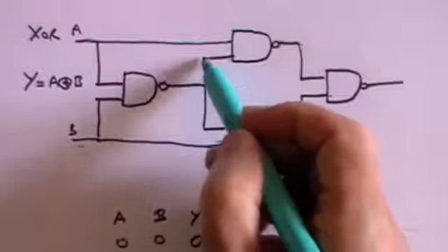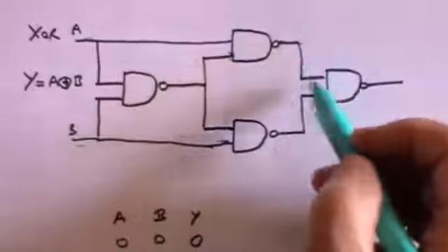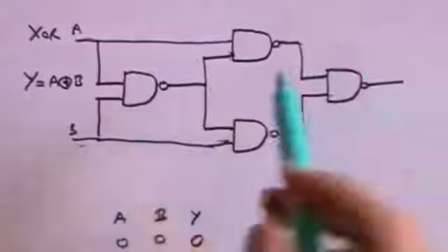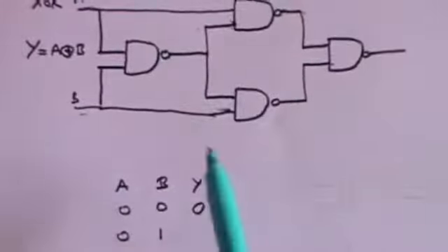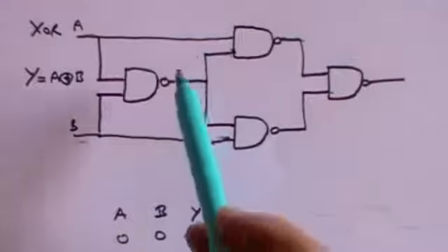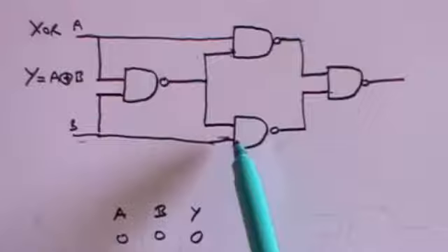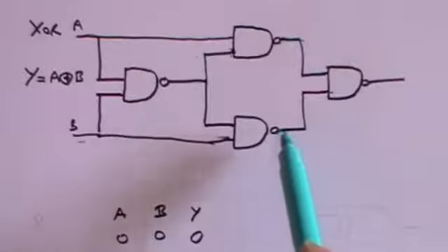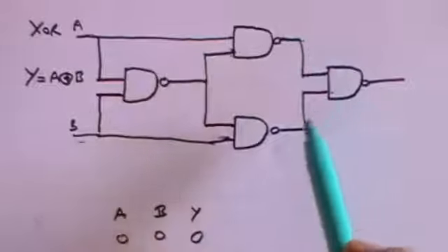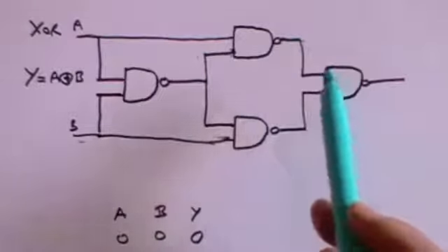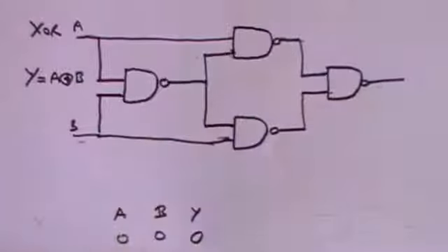A positive out coming in here together with a 0 from A will give you a positive out. So that's a positive coming in here. What about at this end? Well, B, we said, remember, is positive. So B is positive. The output from here is positive. So we've now got 2 positives going in. That means you're going to get a 0 coming out. You had a positive coming in here, a 0 going in here, a positive and a 0 will give you a positive output.